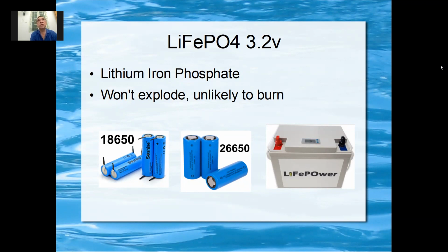You will get into problem, because when one of the batteries is weak, then this battery cannot be fully charged, and it will remain not fully charged forever. It's just like you put 4 people on a table, and then you provide the food. The stronger one will always eat most of the food.